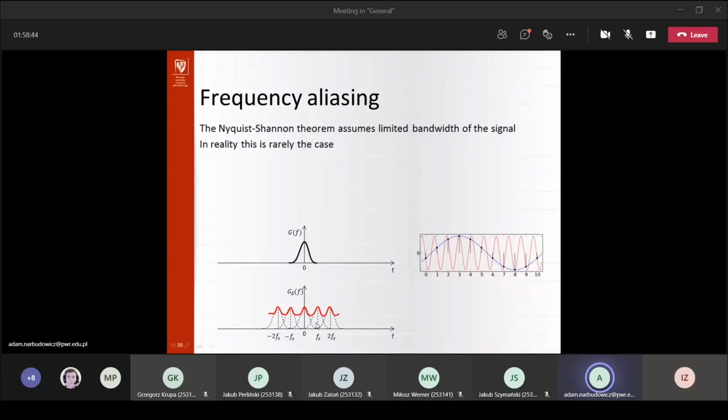So this basically means that if your sampling frequency is less than double the signal frequency, you would have a thing called aliasing, which means a portion of your spectrum will overlap, or 2 portions of the signal will overlap.